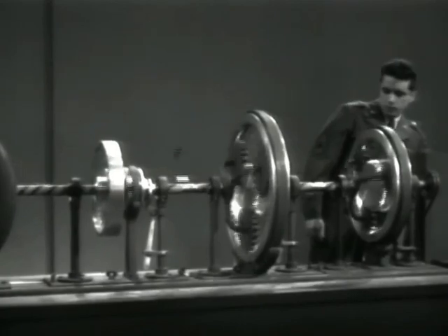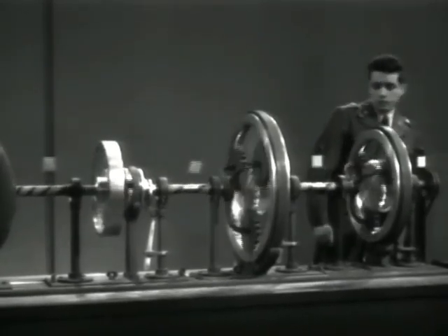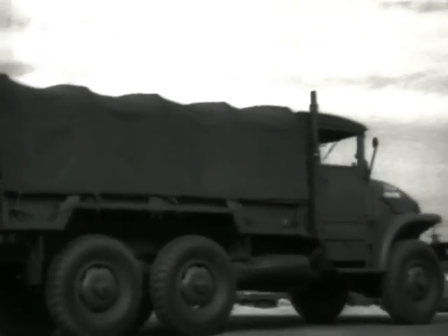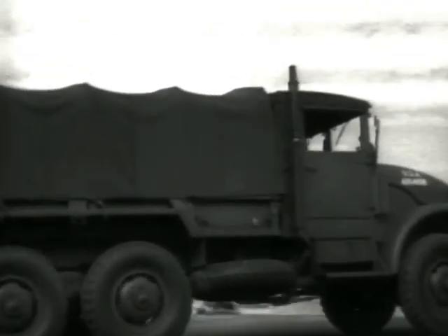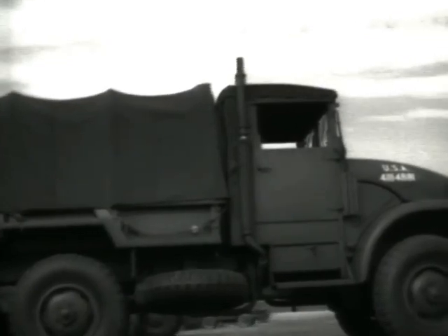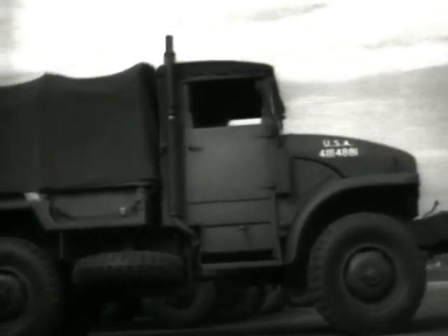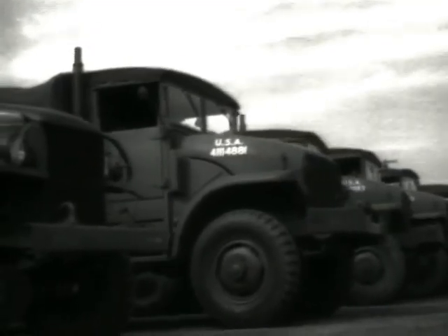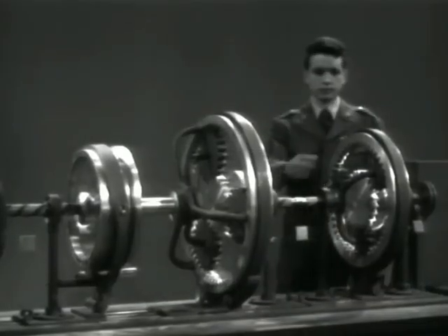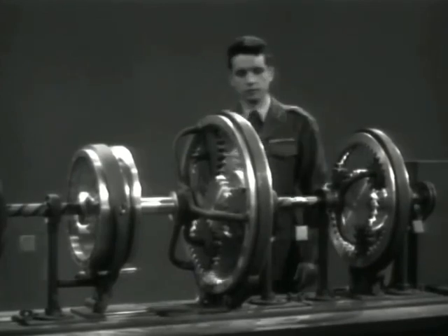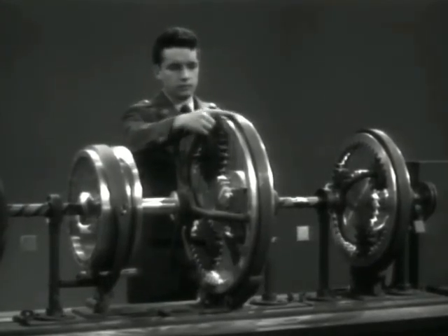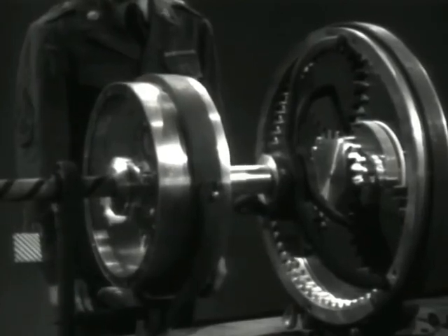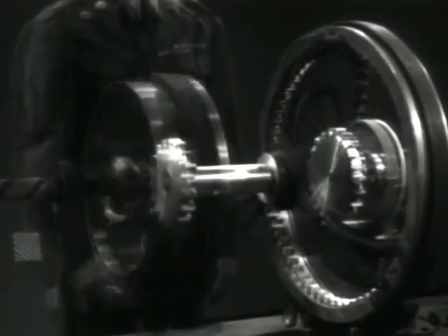Actually, such a reverse would be too bulky. Space and weight can be saved by using what is called a compound reverse, which you'll come across in certain truck transmissions. With our compound reverse model, let's keep in mind that this is our front set, this is the intermediate set, and this the reverse unit. To see how this works, let's build up the compound reverse unit step by step.